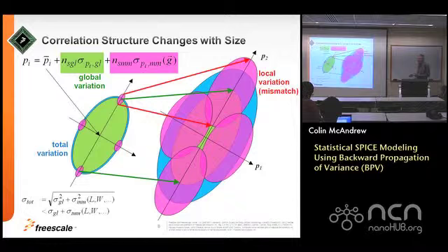gets significantly larger. And the error that you will always see when people show this chart is that when I'm looking at the total variation, which is the blue ellipse, they will make it line up with the perimeters of the purple ellipses here, okay? And the cardinal rule that you must always remember about adding standard deviations is that you can't. You always add variances, you don't add standard deviations. So the total sigma is the square root of the sum of the squares of the variances, which is less than the sum of the standard deviations.